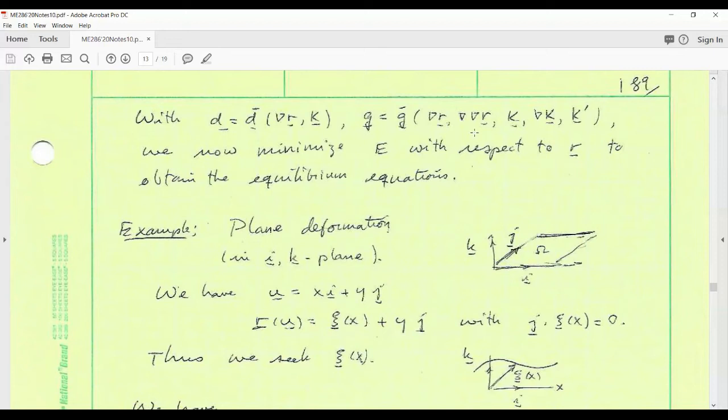You may have heard of strain gradient elasticity. That's a theory of elasticity in 3 dimensions that involves F, which is the gradient of deformation, and the gradient of F, which is the second gradient of deformation. Well, interestingly enough, the plate theory emerges as a second gradient 2-dimensional theory. That's another manifestation of the additional complexity of the 2-dimensional model. It sounds like a retrograde step. We've replaced a relatively simple model by a more complex one.